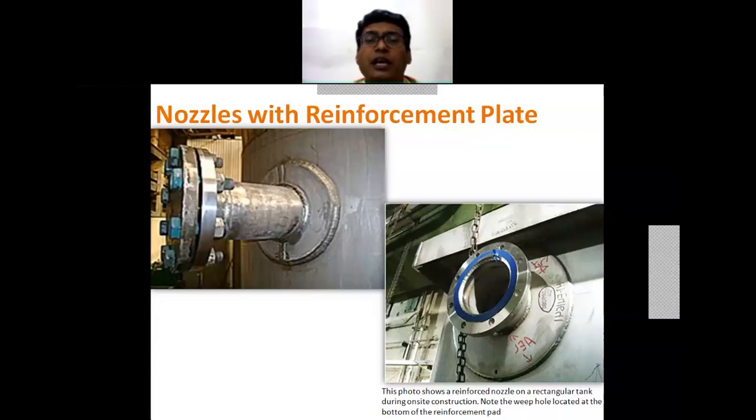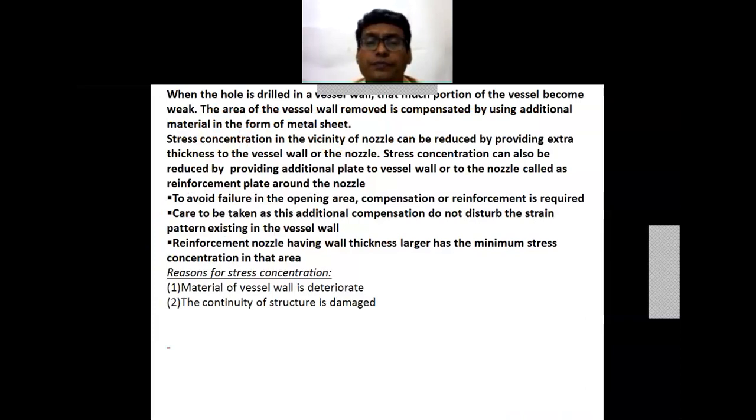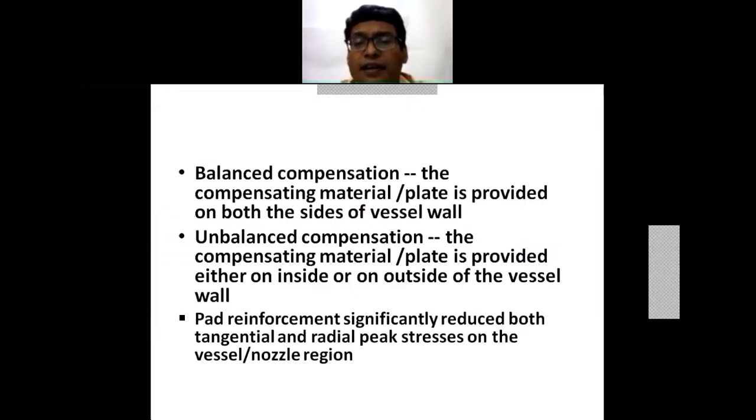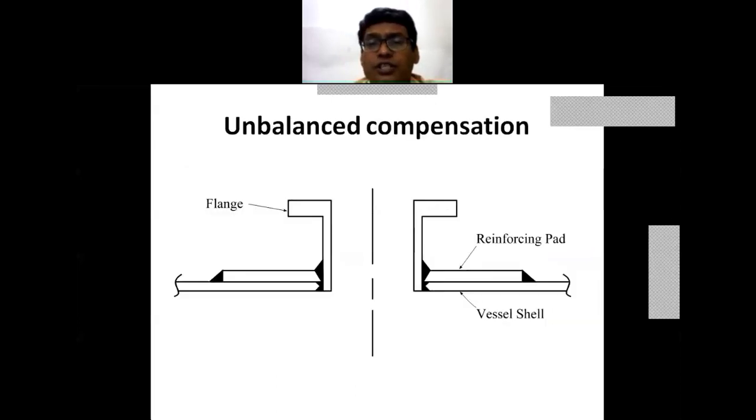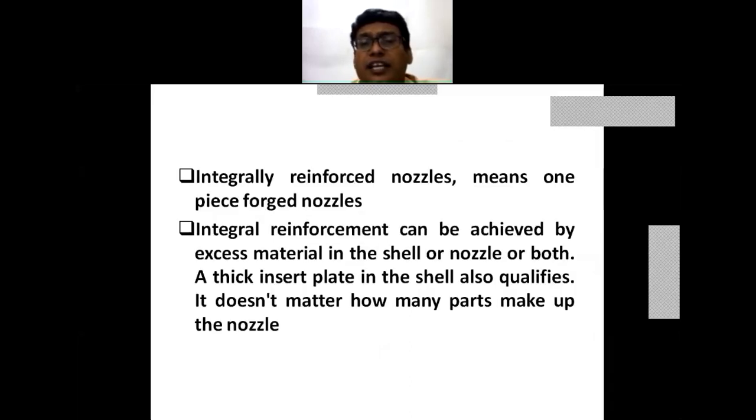Mostly outside welding is provided because of the ease of operation. The pad reinforcement significantly reduces both the tangential and radial stresses on the vessel and in the nozzle region. Then there are integrally reinforced vessels, which means a one piece forged nozzle.